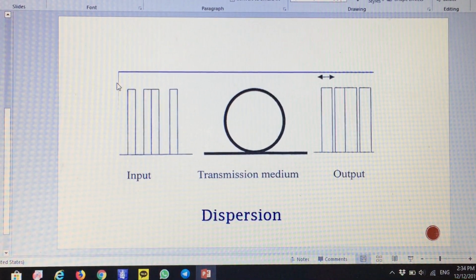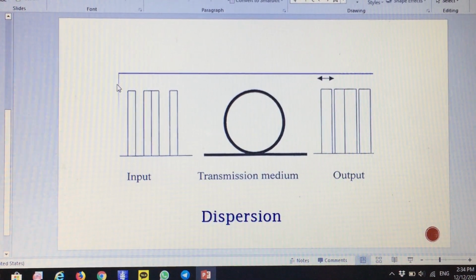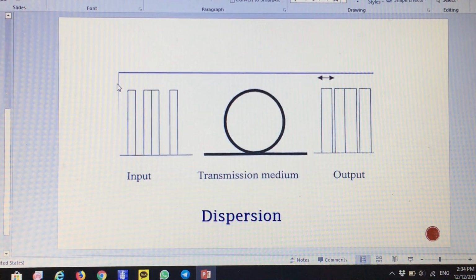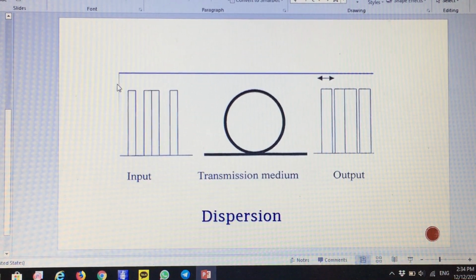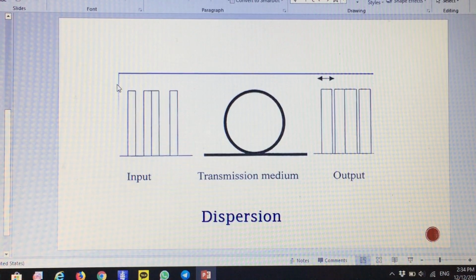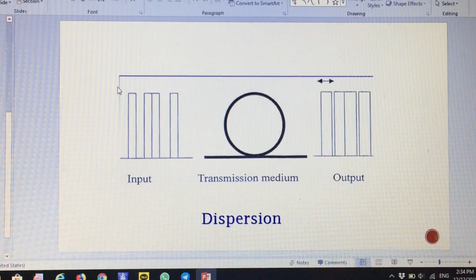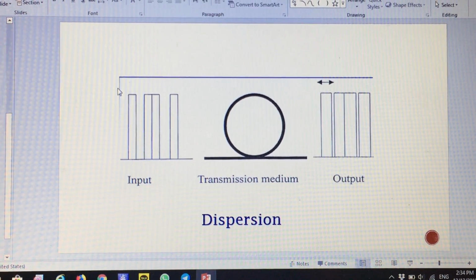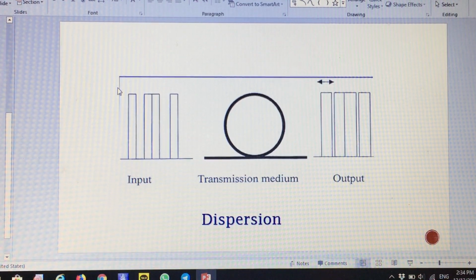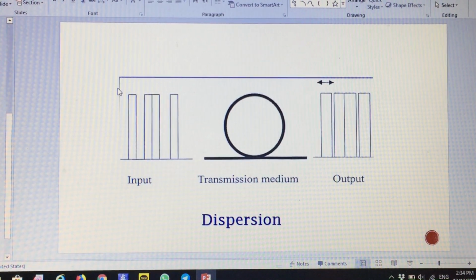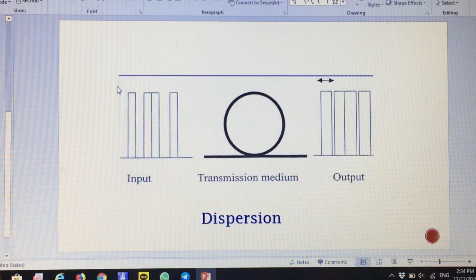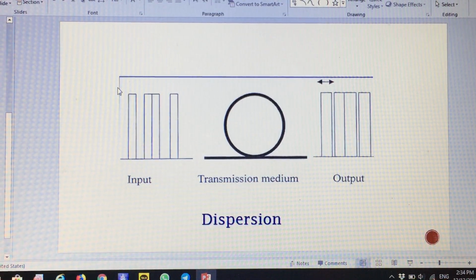The other one is that optical fiber nonlinearities can be significantly reduced by increasing the effective mode field area. This can allow system designers to increase launch power for more transmission distance or higher bitrate signals or both.